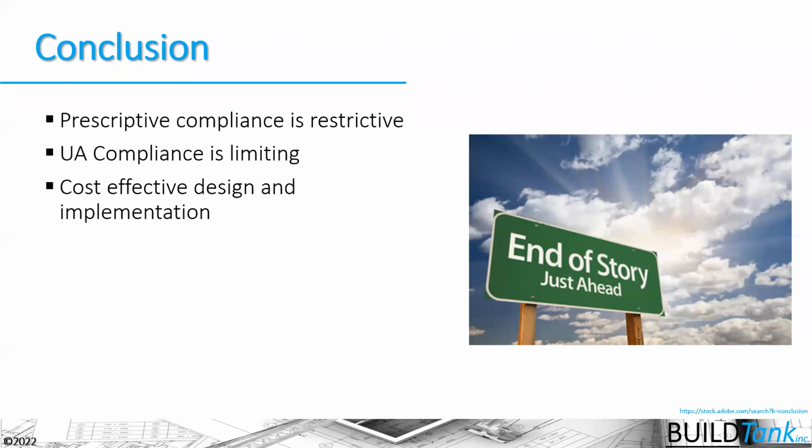So one of the interesting things that I'm learning in my work with the Marshall Fire rebuild is that the majority of the builders are custom builders. And the majority of the time, they are myopically focused on the R value table there, which is not allowing them to figure out the most cost-effective way to meet the intent of the code.